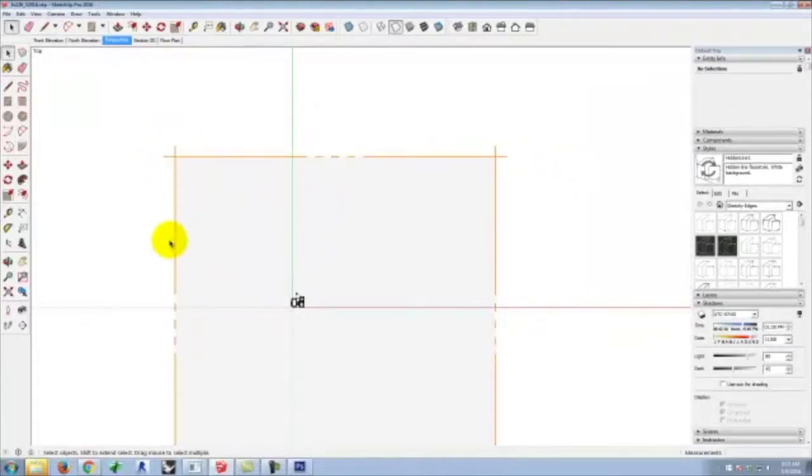And you see how, well, on the projector you can't really see it. On your screen you'll see it, that it's slightly gray versus the plain white of the background. So I need to make sure that I turn this off. I'm going to go to View, and I'm going to uncheck Section Planes. And it's going to turn that section plane off. I can't see it anymore, but it also makes it so that it's not that light gray. When we do the Photoshop post-processing, if you leave it on, it will make the background progressively darker. And you won't want that when you layer them together and use the multiply.